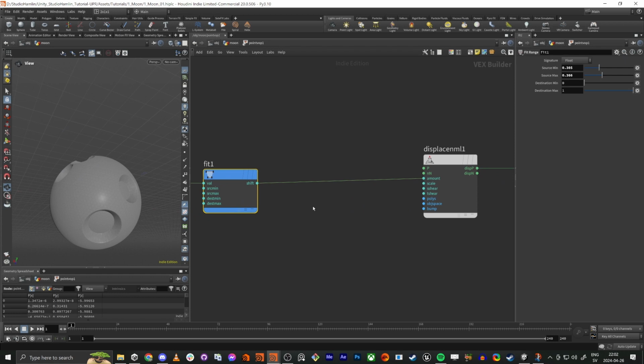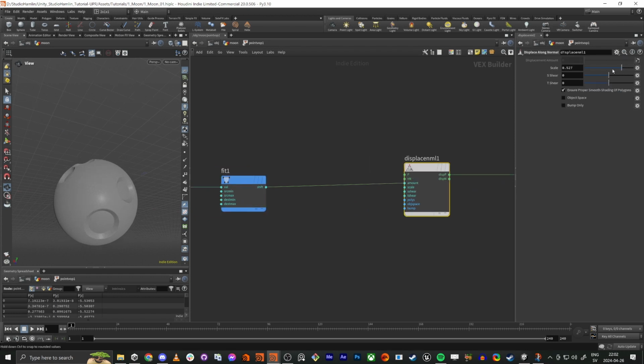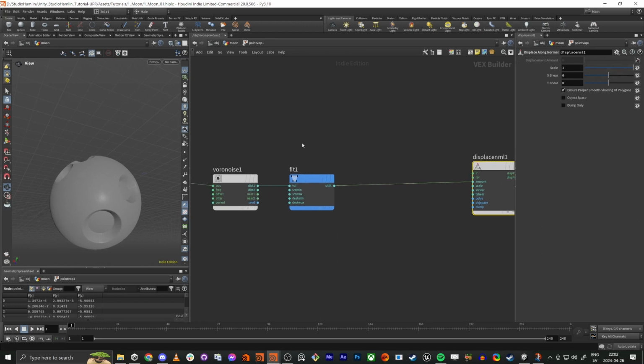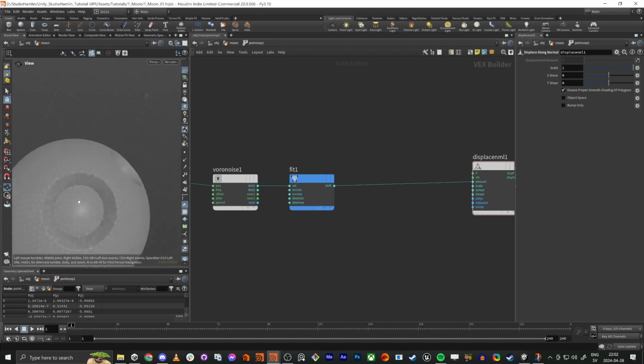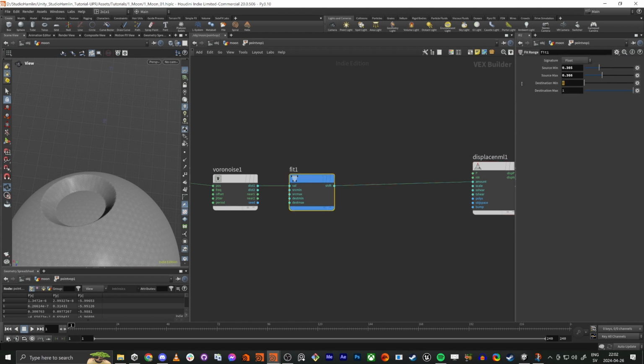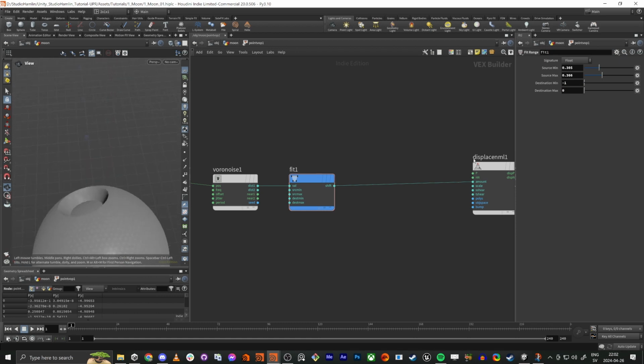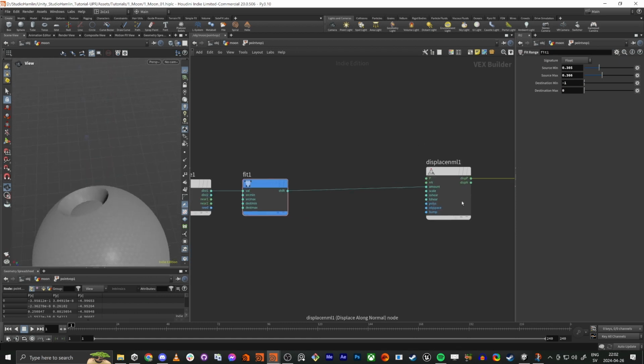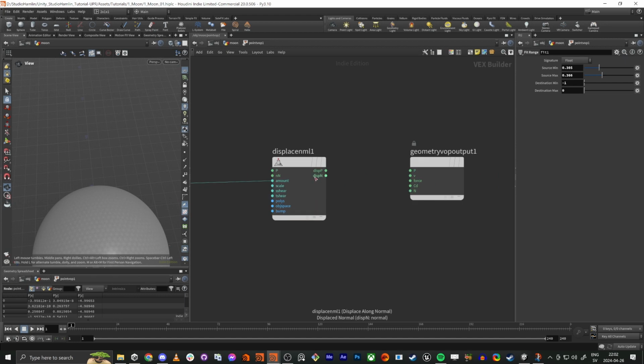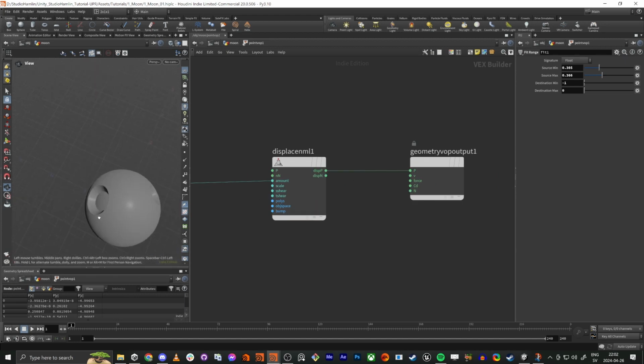But what's actually happening here is that we are kind of extruding everything except the holes. And that's not how I want it. I want it to be more extruded down. So you could, for instance, do like this, and then you get the holes. So if you see what I mean here, if I just do like this, now it's working the way I want.